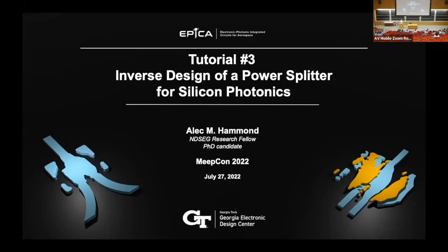Yeah, the tricky part, I tried to articulate this. Let me see if I can do a better job. When you compute the equivalent time domain profiles from your frequency domain quantities, we essentially do a fitting problem. We take a bunch of Gaussians or filter windows that we have to put together. And the width of those Gaussians in the frequency domain depends on how densely packed your frequency points are. So if you need to simulate frequency points that are really close together, we need to resolve those frequency points, which corresponds to really long time domain simulations. So that's the natural trade-off. Again, it's a Fourier uncertainty principle at that point, right? Yeah, good point. Yeah, Ryan?